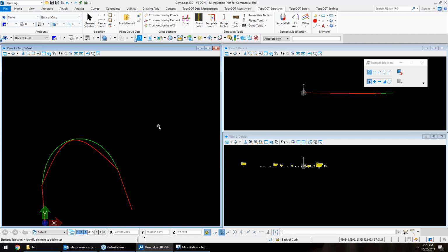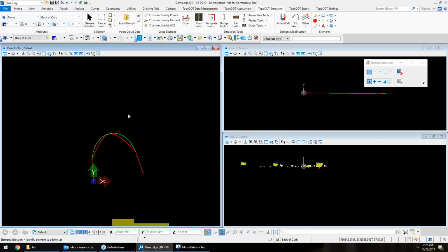Obviously, one of the reasons you pick line segments or splines, and correct me if I'm wrong, I think is just how your DTM engine handles it. Some might like splines, some may not. Some want the line segments, which work better when you're making your DTM. So you just have to experiment a little bit. But you have a lot of tools there to do that.